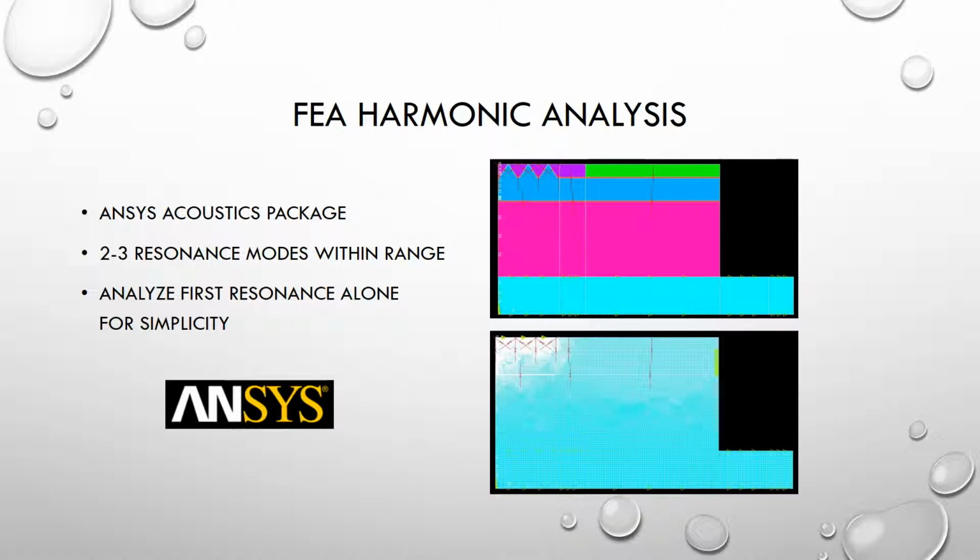The 2D finite element analysis domain used is shown at the right. The piezo, aluminum, fluid, and silicon materials are represented by the light blue, magenta, blue, and purple areas respectively. The green represents a plastic boundary that holds the silicon chip in place.